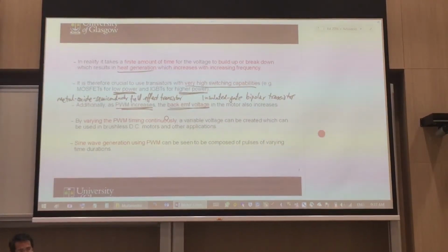So this PWM is used to generate an effective voltage output to your motor, and this effective voltage maintains its polarity. That means I can lower the effective voltage by having PWM. But if you are interested in changing the polarity, that means having a plus-minus kind of sinusoidal wave as a PWM to your motor, that's also possible.